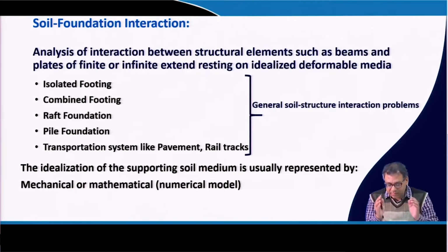These interaction problems can be useful for the design of isolated footing, combined footing, raft foundation, pile foundation, and transportation systems like pavement, railway tracks, and airport runway. Those can be modeled by using these interaction techniques. The idealization of the supporting soil media is usually represented by a mechanical, mathematical or numerical model.